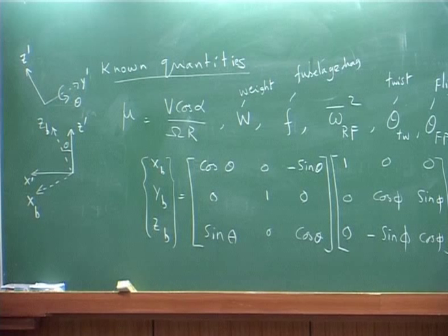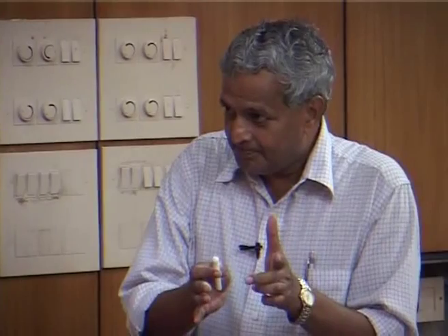Gyro will give you rate. Okay, that I will come to later. Gyro will give you angular velocity. Angular velocity is a vector, because it gives you the instantaneous angular velocity about 3 axes. If you have a 3 axis gyro, it will give you rotation about the 3 axes. Now, the rate of change of attitude, please understand, there is a lot of difference between the angular velocity vector of the body at an instant and the rate of change of attitude of the body. There is a relationship. If the angles are small, you say angular velocity is the same as the rate of change of angle.